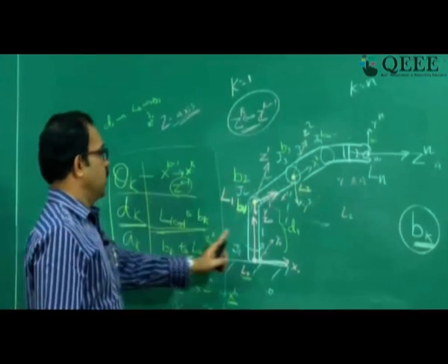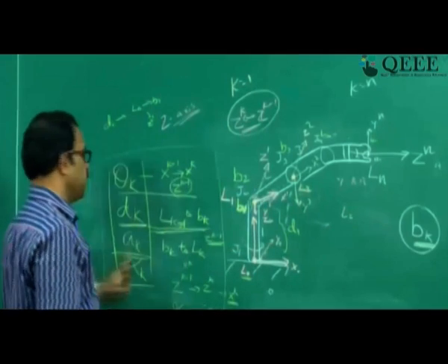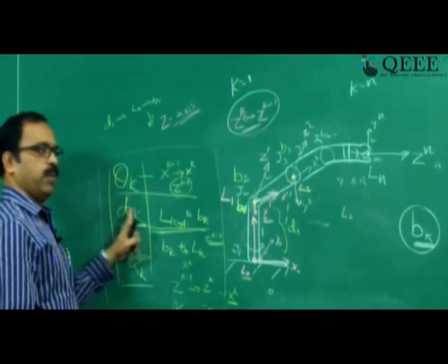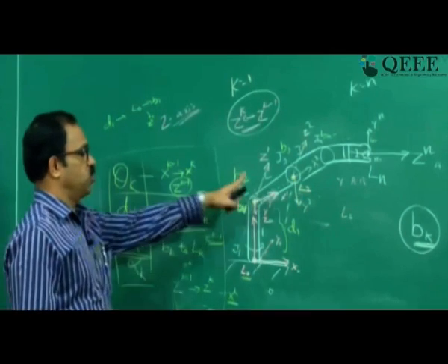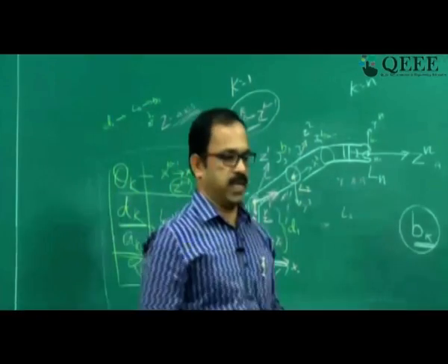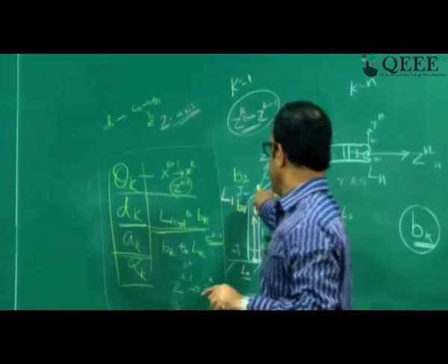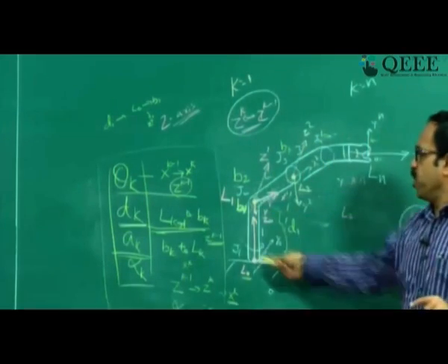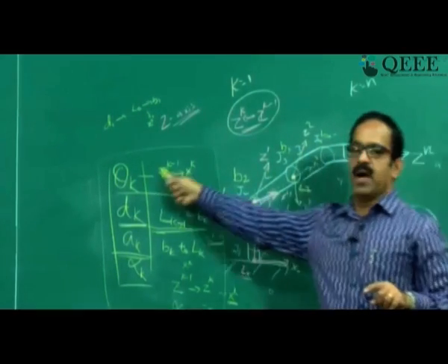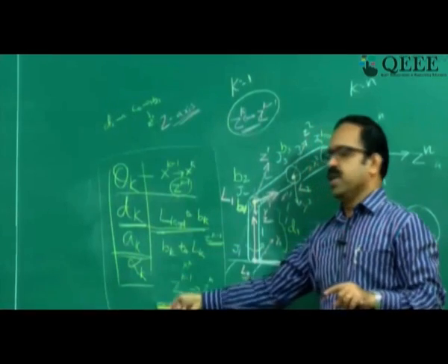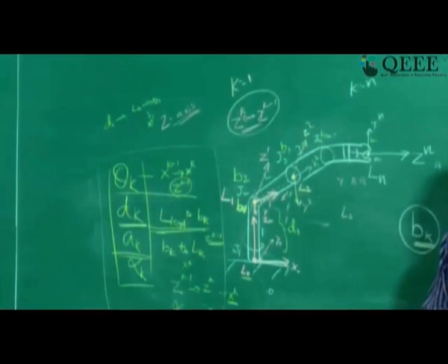So if you have n joints, you will be able to identify n sets of DH parameters corresponding to the given manipulator. That is the DH algorithm which helps us assign coordinate frames and get all the kinematic parameters necessary for defining the complete kinematics of the manipulator.